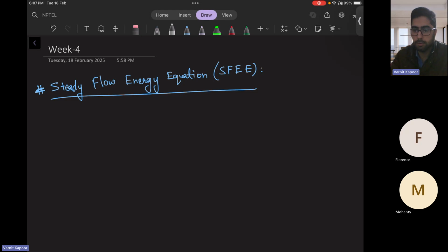You know very well what an open system and a closed system are; we have discussed them in detail in our previous tutorials. Working under steady conditions, steady means that it doesn't change with respect to time. That is where the rate of mass flow and the energy flow are constant with respect to time. So the property does not vary with respect to time. Whatever the mass is at entry and exit will be the same.